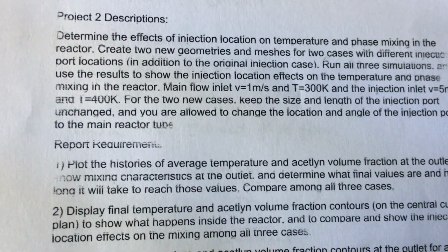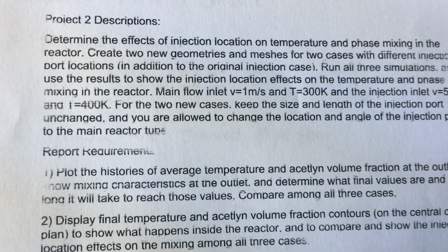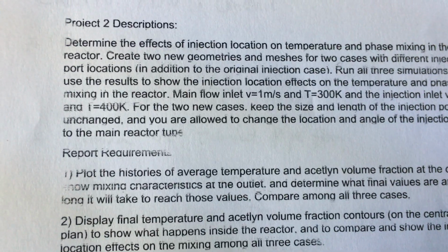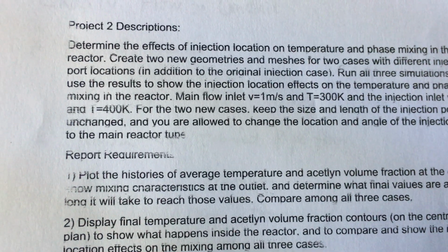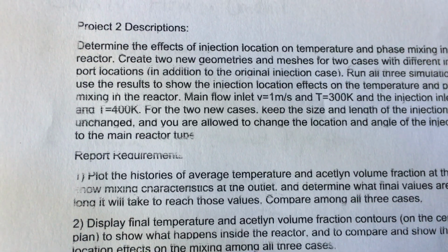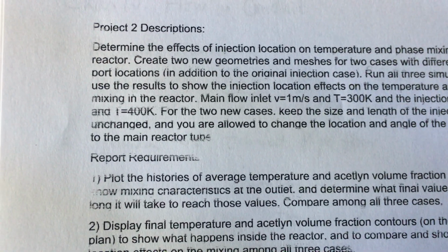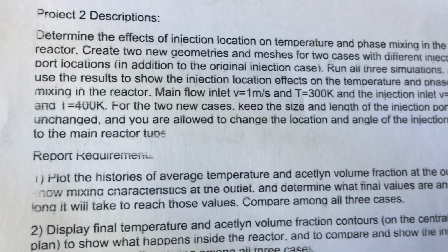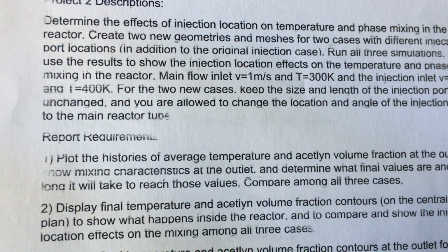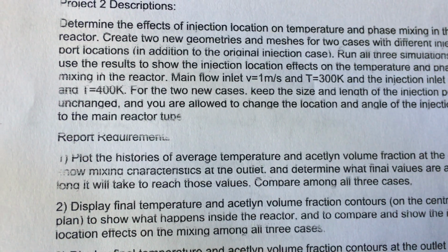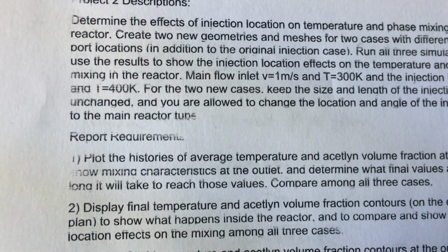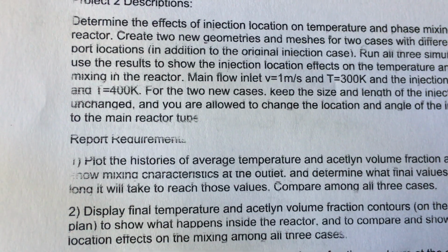On each grid point, the simulation result will give you a volume fraction, which is between 0 and 1. Combining these two fluids, it will be 1, which is 100%. That's the value we want to look at, to show on each surface or even each cell what the percentage of ethylene and the percentage of acetylene is.